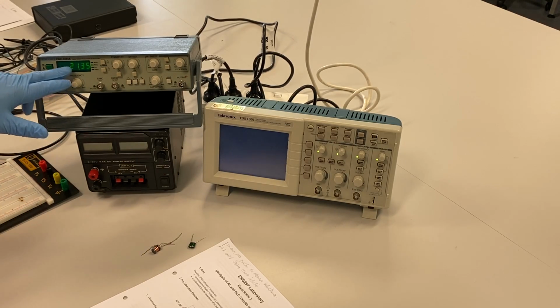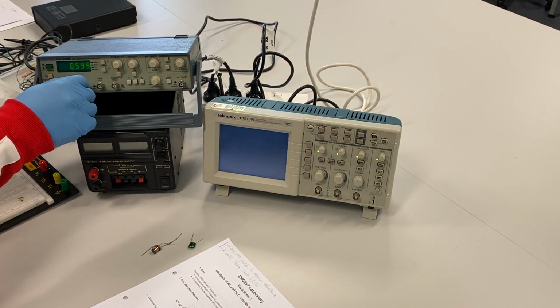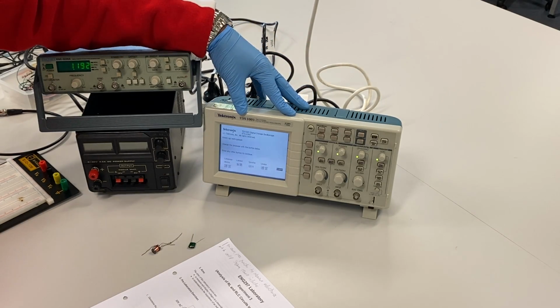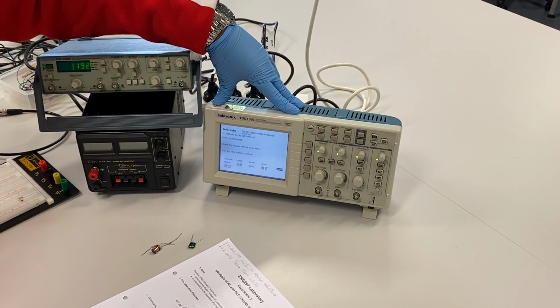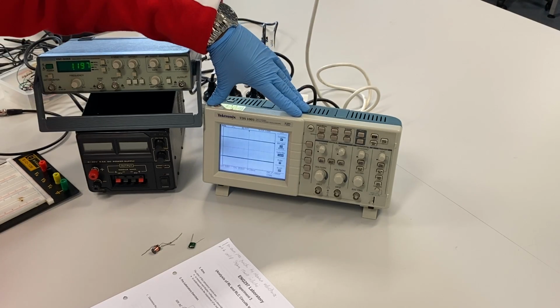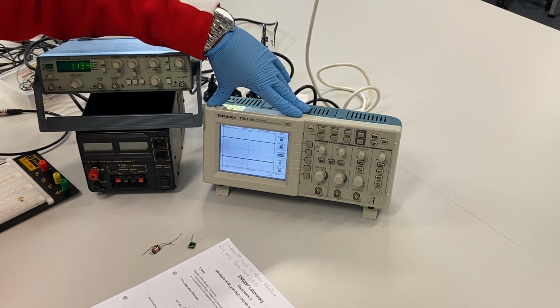Like I said, the function generator just displays the frequency on this display. So you can turn this knob, right? It gives you different ranges of frequencies. The oscilloscope is more like a graph paper, right? In its original setting, the oscilloscope displays voltages. It doesn't display current, but for those who were in the first lab, there's a way of displaying current on the oscilloscope, but it's originally designed to display voltages. It can display input voltage, output voltage, depending on whatever voltage you're measuring across different components.